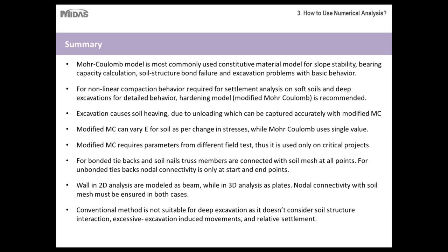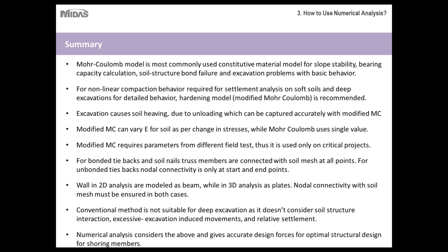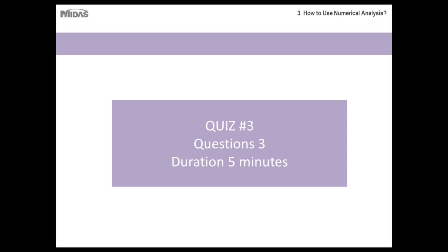And the conventional method is not suitable for deep excavation as it doesn't consider soil structure interaction, excessive excavation induced movements, and relative settlement. So therefore, numerical analysis is used which considers the above and gives accurate design force for optimal structural design of your shoring members. I hope the points are duly noted.